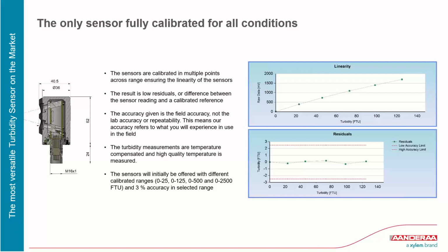In the upper graph, you see the relation between the FTU, turbidity units, and the raw data response of the sensor. Then, after calibration and before every sensor goes into the field, we verify how well it performs with respect to the specifications that we give, which you see in the lower graph.